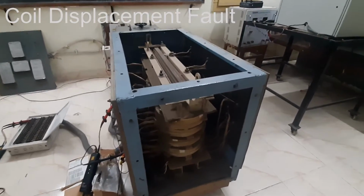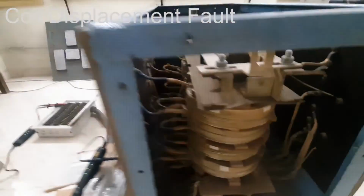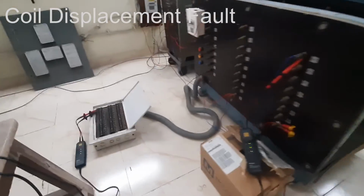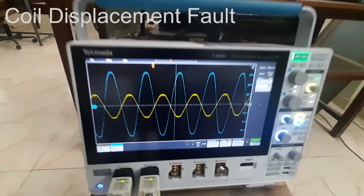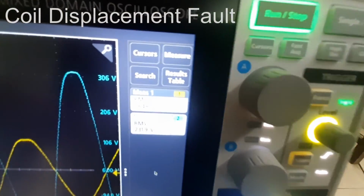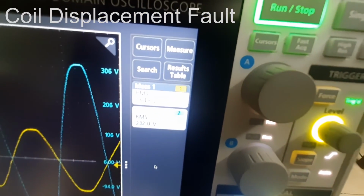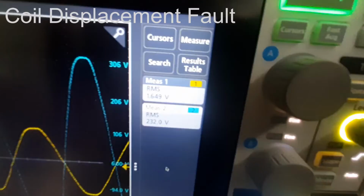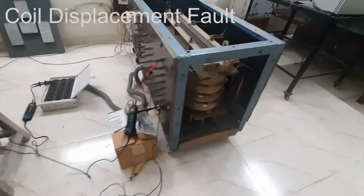Now we will see the coil displacement fault. In this case, what should be the search coil voltage and your input voltage? So you can see here the input voltage and the search coil voltage. You can see here 31.9 is your input voltage, and 1.65 is your search coil voltage.